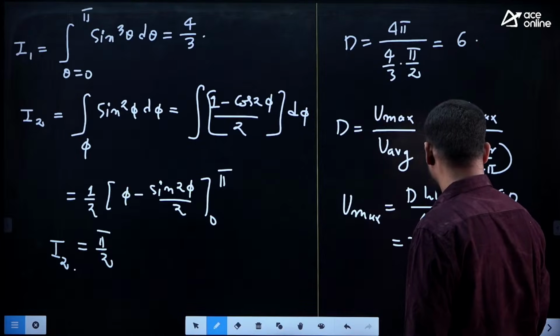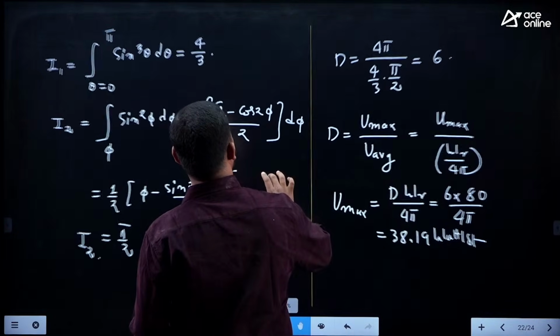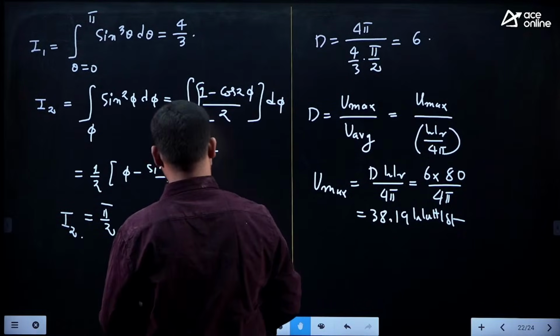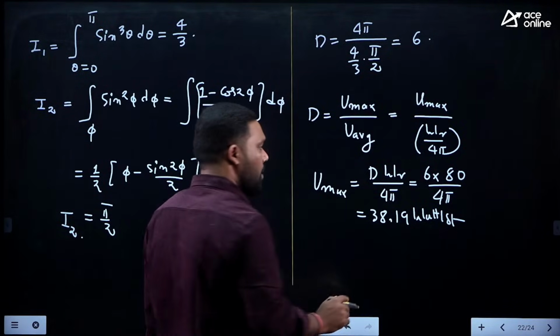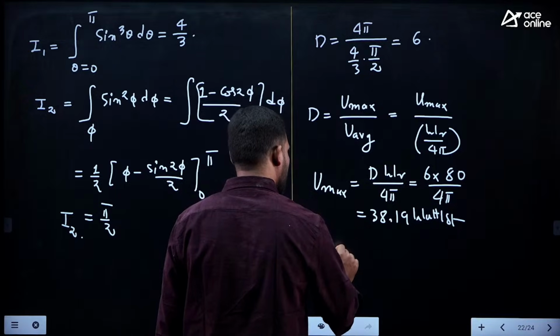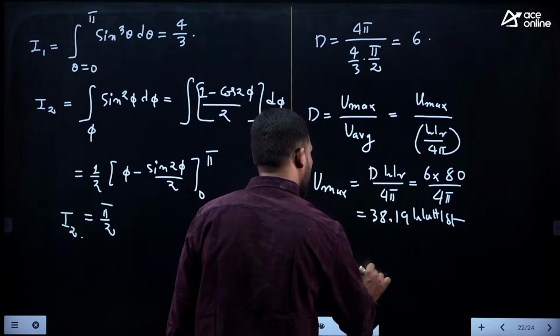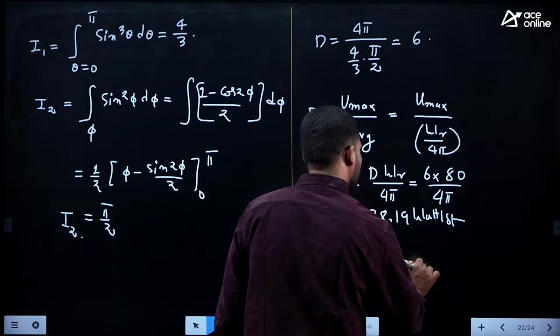Next, power density along the direction of the maximum radiation. How do you find out the power density? Power density and power intensity. So maximum power density is asked. So what is the power intensity, guys? It is power density into R square.